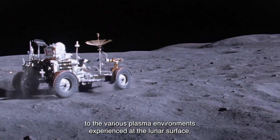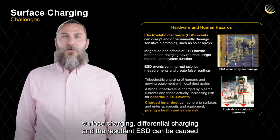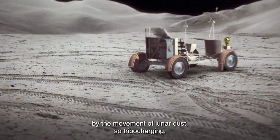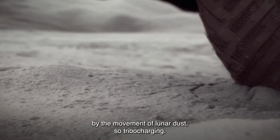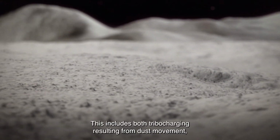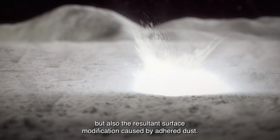In addition to the various plasma environments experienced at the lunar surface, surface charging, differential charging, and the resultant ESD can be caused by the movement of lunar dust, so tribocharging. This includes both tribocharging resulting from dust movement, but also the resultant surface modification caused by adhered dust.